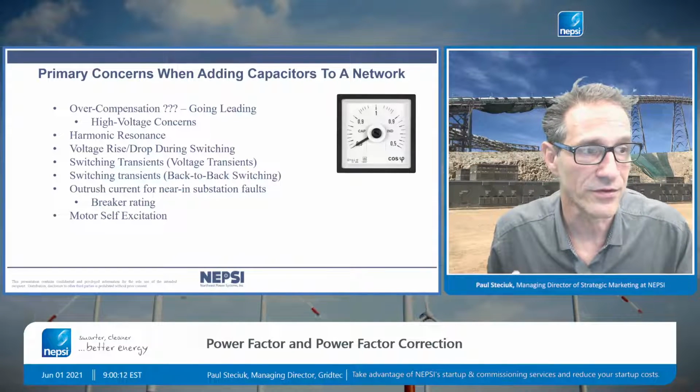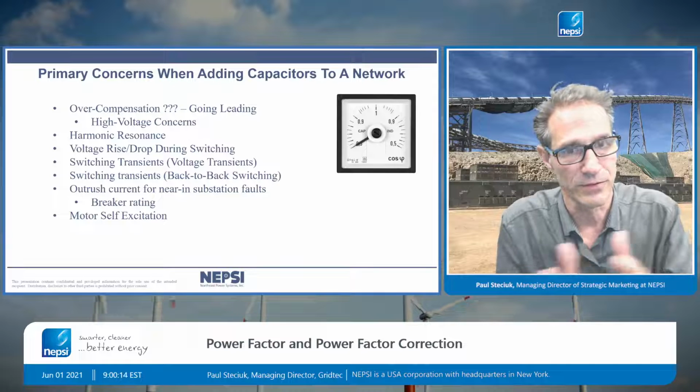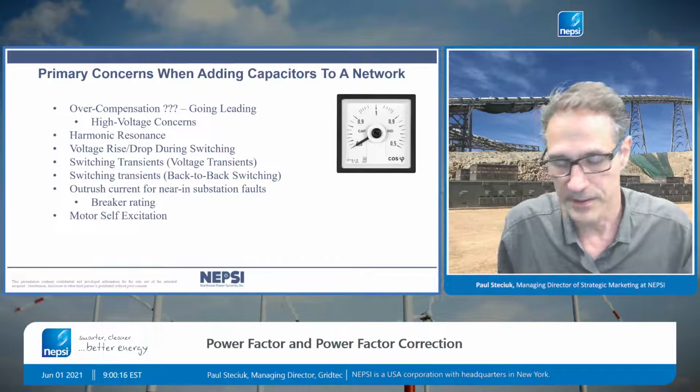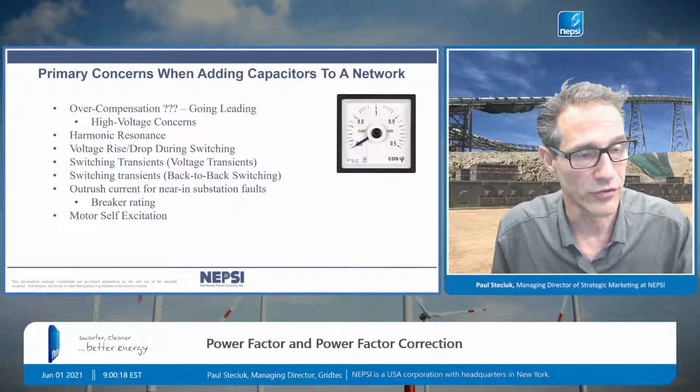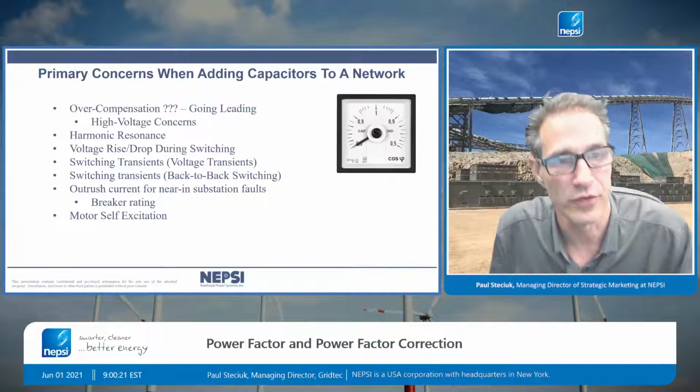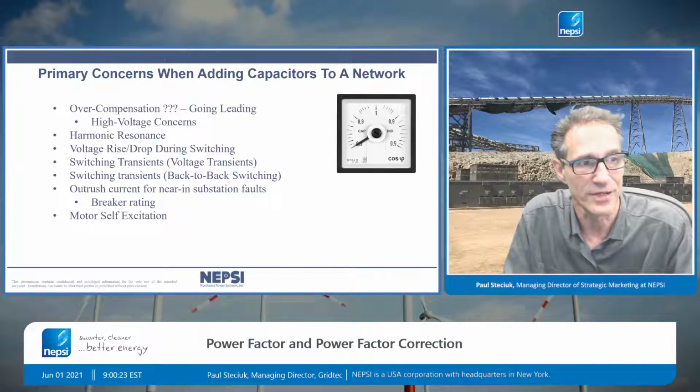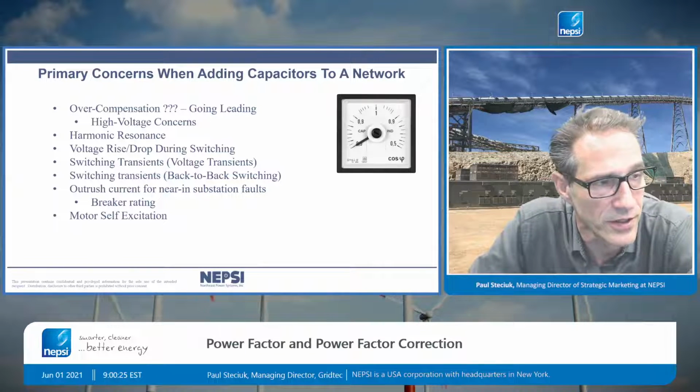You might want to even consider 2% voltage rise. So we split the bank up into smaller pieces by coming up with, well, what creates a 2% voltage rise, or what creates a 3% voltage rise. Typical situation that you got.